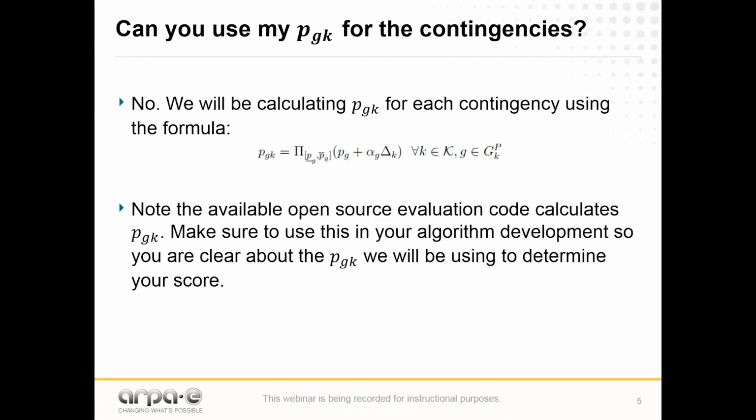We anticipate all generators to follow their participation factors for the contingencies that they're supposed to respond to, as long as they don't reach a bound. So I follow my participation factor until I reach Pmin or Pmax, and then at that point I just sit at Pmin or Pmax, and whatever I was expected to produce that I cannot produce, essentially through the formulation we've structured, gets built into other generators and their participation factor, right?